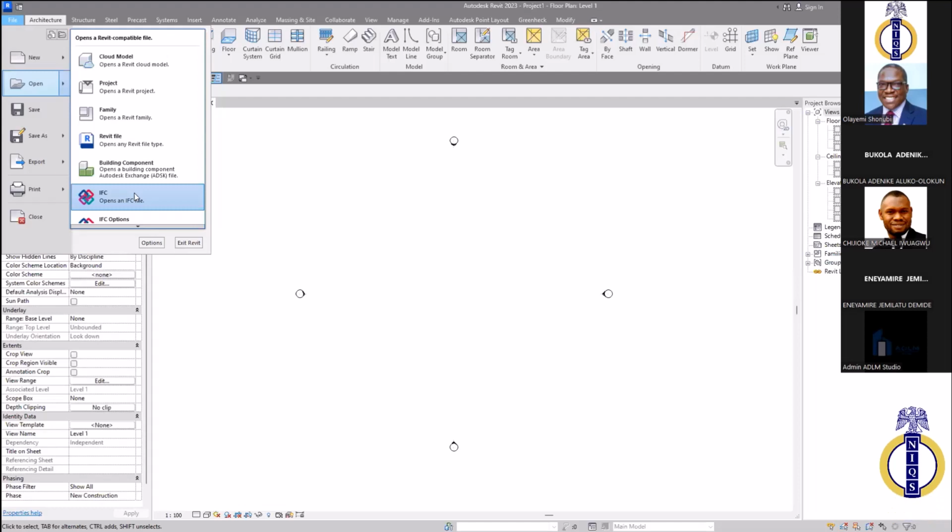So you're taking the 2D drawings and all of that. You need the 3D model. All you just have to do is tell the architect, okay, Mr. Architect, you're using so-and-so software. Convert to an IFC file. You as a QS, open up your Revit, open up the IFC file, and you can do your quantification. As easy as that. Do you understand? So that is the IFC file.